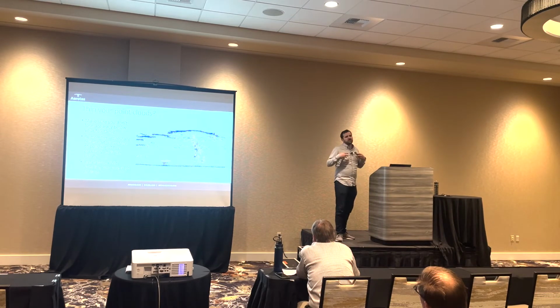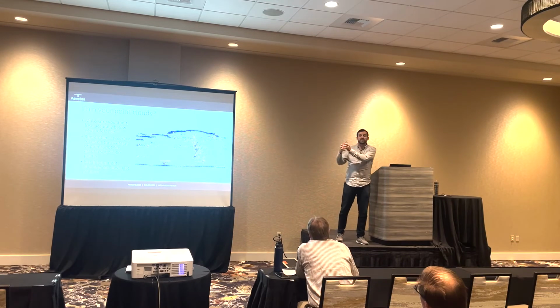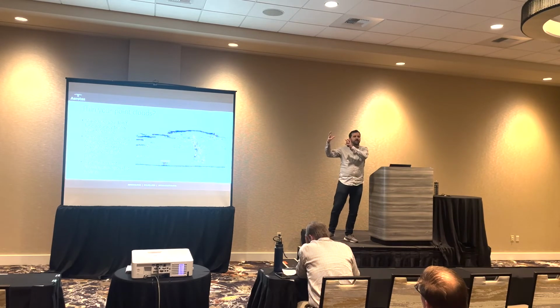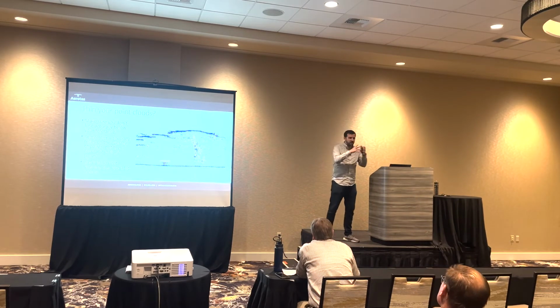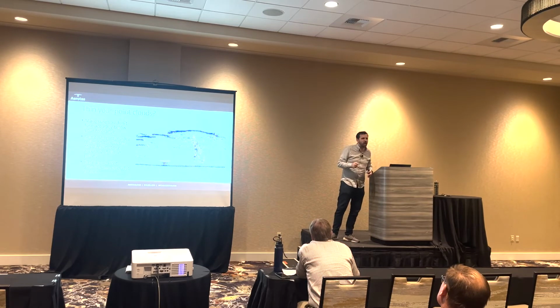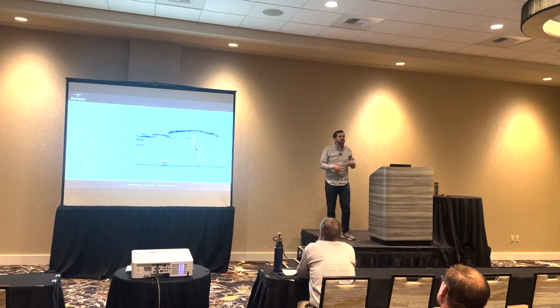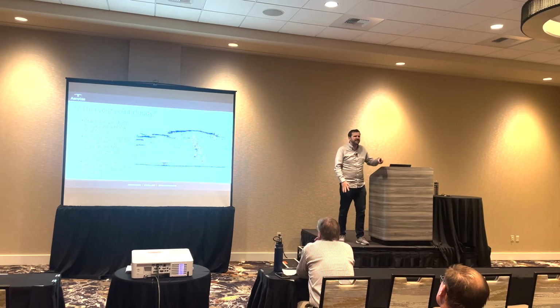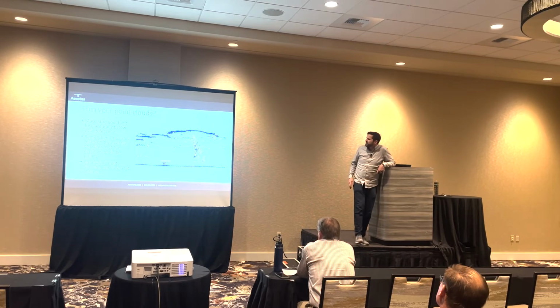So there are methodologies to do 3D thinning, where the more dense the points, it effectively breaks your project up into individual cells. It says if there are 1,000 points in this cell, I'll cut it down to 1, and if there are 2 points in this cell, I'll cut that down to 1. That works as well, but if you use a low resolution, it can create some artifacts. It usually can introduce up to 1/10 or 2/10 of a foot of error, even in some cases.